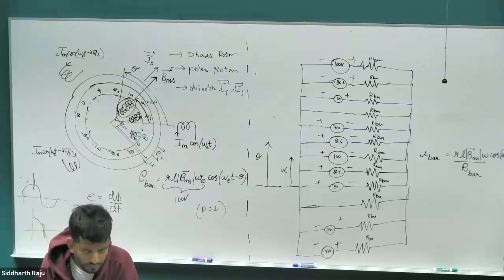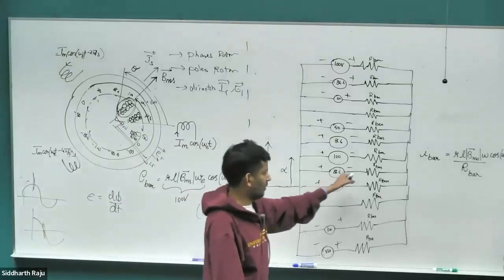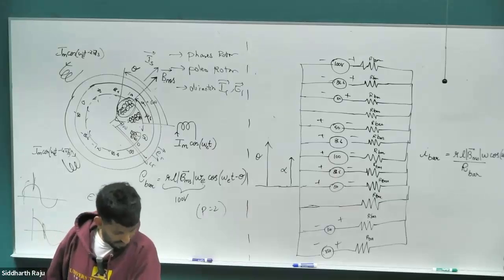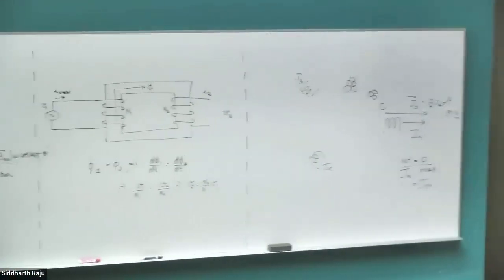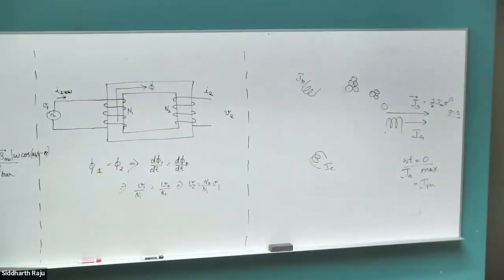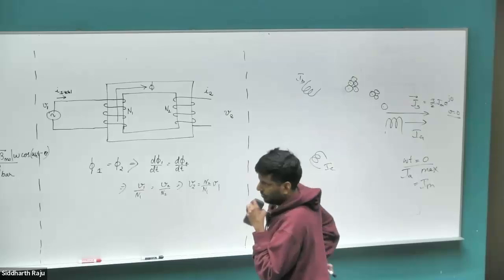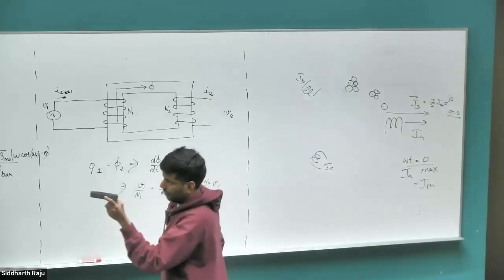Yep. Are the rotor current and EMF in phase because you're neglecting any inductive effects? Yep. I'm just starting off with rotor resistance alone. We'll bring the inductor in just a little while. Okay. What will be the source of the inductance? Loop area? The loop area. Would it be part of? Let me not jump the gun. I'll get it.